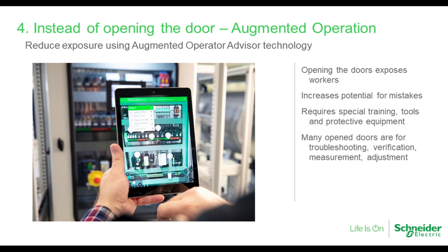That's usually hidden. So we see this a lot when it comes to troubleshooting. Before I was at Schneider Electric, I worked in electrical maintenance, and I worked with some medium voltage equipment. You sure don't want to open up that door while it's live. If you do need to open it up, you need special equipment that you're going to wear. You're going to need a lot of signatures. Usually it just doesn't happen, right? So if you need to see inside something that is medium voltage, the answer is probably no.